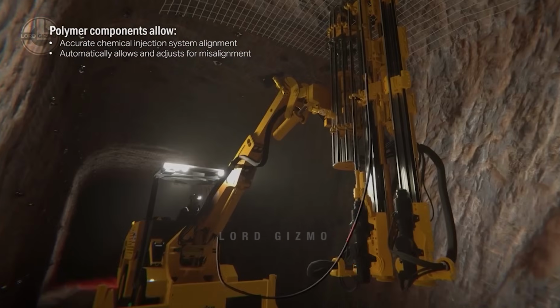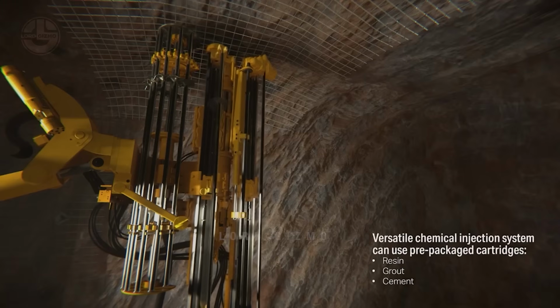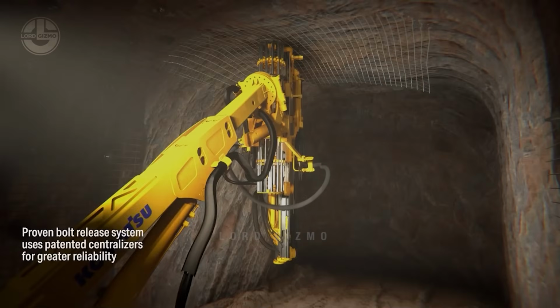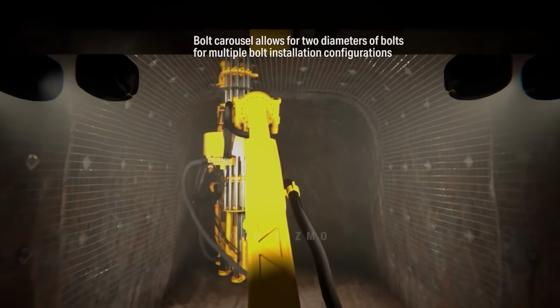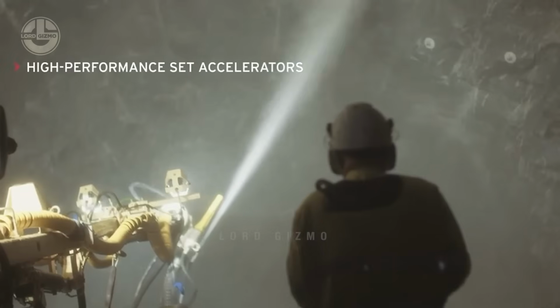The most common form is mechanically anchoring a rock bolt through an expansion shell. As the bolt rotates, a wedge fastened to the bolt shank is drawn into a conical expansion shell. As a result, the shell is forced to enlarge against the borehole wall. The purpose of this is to provide support for the roof or sides of the cavity.